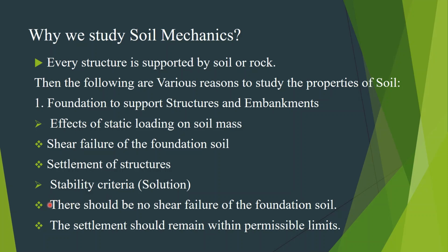We check that there is no shear failure of the foundation, and that the settlement remains within the permissible limits. For the foundation to support the structure and the embankment, we must check the effect of the static load on the soil mass and the stability criteria.